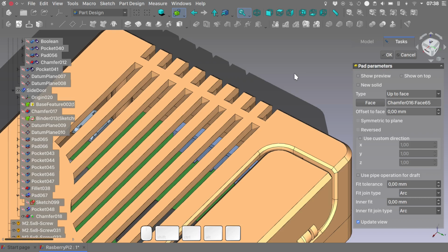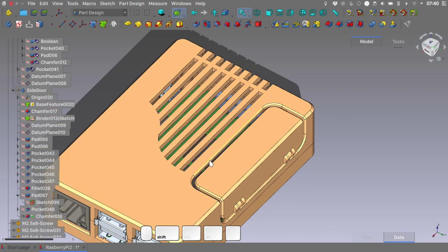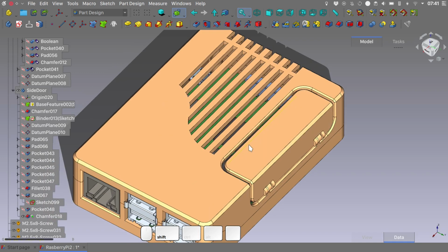But in this iteration of LinkStage3, and I wanted just to remind everybody that this is trickling down into the master now, thanks to great efforts from the developers. Now, just by confirming the path and letting FreeCAD do its magic, the new toponaming algorithm will correct, or at least do its best to correct the errors that come after it. In my opinion, this is really a game changer for FreeCAD. I will model now some sort of support here for our door in order for it to not fall down inside the case, and then we will take on a quick assembly of our components.